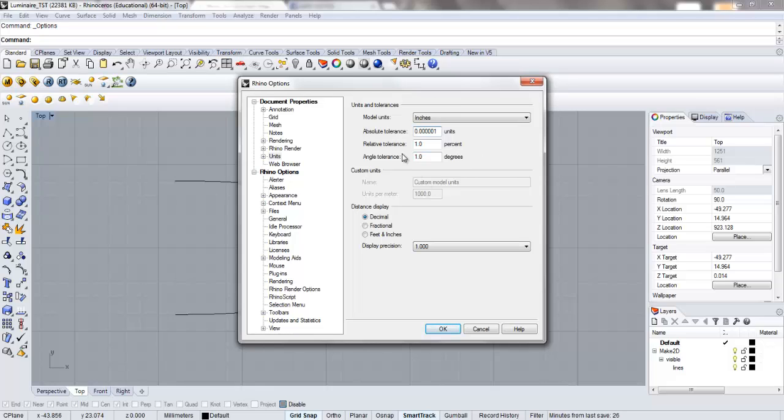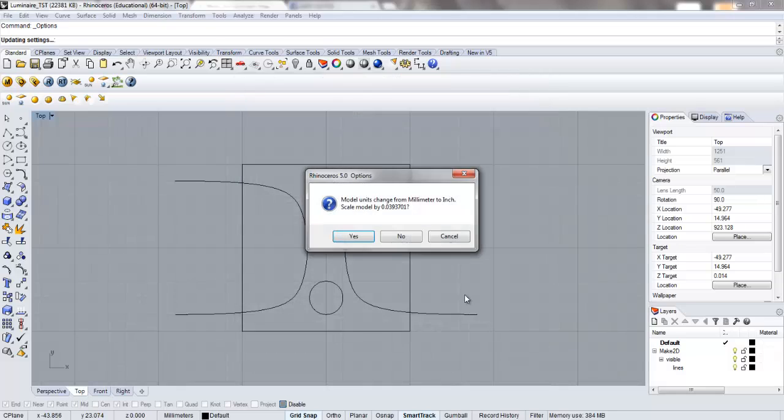If you guys are having trouble with something that you know should be connecting or should be trimming or splitting, that's going to be something you're going to want to pay attention to. Okay, and it could be that this is the problem. Now, if you are in here and you've modeled this and you realize after the fact that you haven't increased your tolerance and that's the issue, you're going to have to go back and remodel that. Unless, and I'm not sure if Rhino has done this, but at least in versions up to this point, that's been a critical issue. If you have modeled something at a lower tolerance, then it's going to remain at that tolerance. All right, so we'll hit OK.